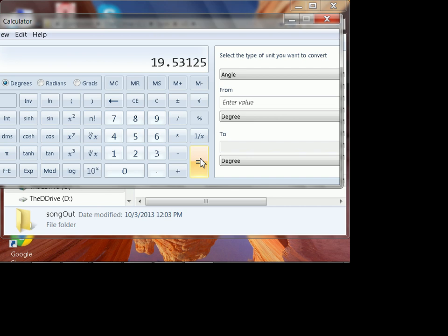If you take this desktop microphone and plug it straight into the ADC without a proper mic preamp, you will hear nothing, nada, zilch, because 10 millivolts is not 5 volts, and it's not even close. It's off by orders of magnitude.